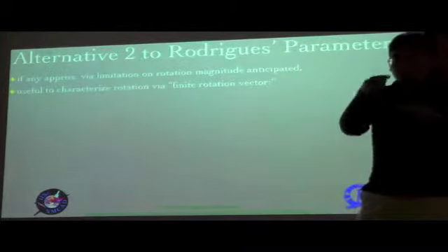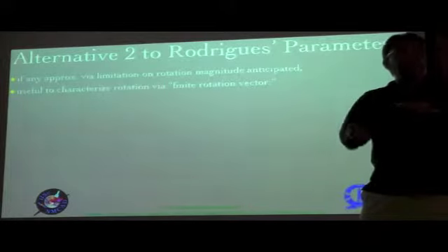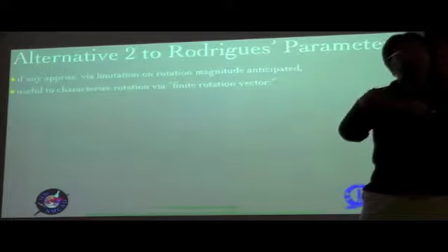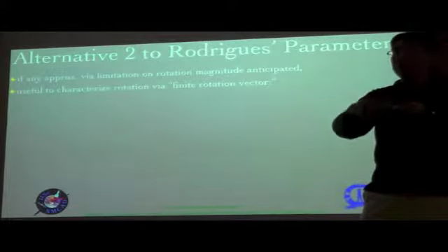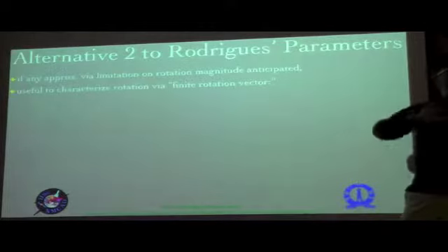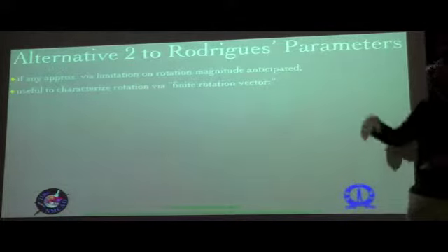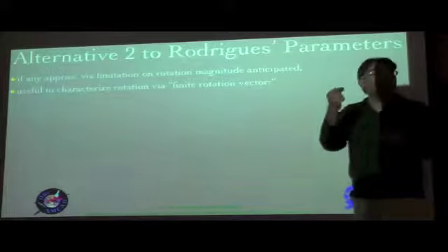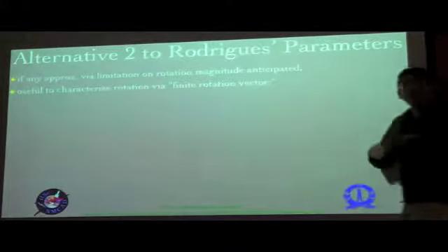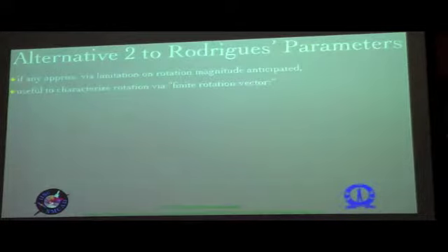Because the warping changes along the length, you take the derivative of that warping with respect to the cross-sectional coordinates, and they are like rotations. Those rotations are pretty small compared to the overall, global rotations that are taking place. So in such a situation, just to represent the local rotations, this can sometimes become useful. It's not necessary, but you can utilize it for computational efficiencies.